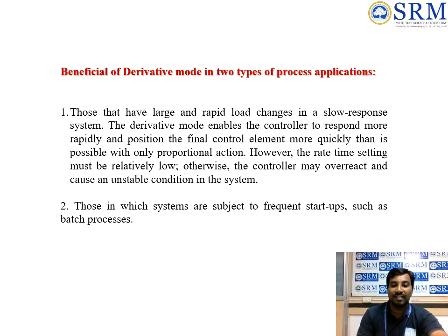So the benefit of this derivative mode is in two different types of process application. Those that have large and rapid load changes in slow response systems may use it. Another is systems which are subject to frequent startups, such as batch processes.